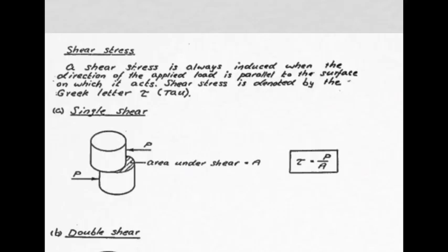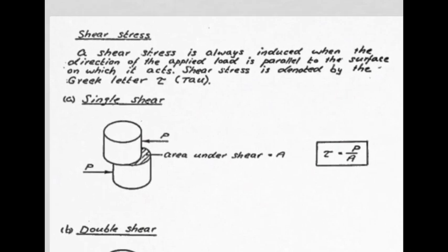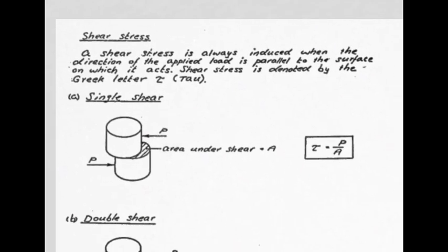So now we get on to the second type of stress that we're going to be dealing with, and that is the one called shear stress. Now, there's a nice little sketch below which shows typical shearing action of a specimen, and you can see that we have the force P pushing the lower half of the specimen from left to right, and conversely the top part of the specimen being pushed from right to left. Now that would cause shear to happen on this shaded plane that we have over here, and amazingly we still have a formula that looks very much like the one for direct stress.